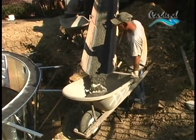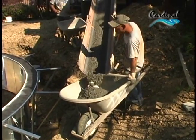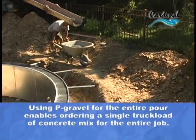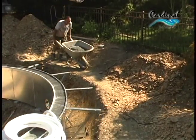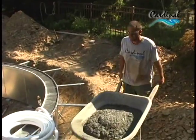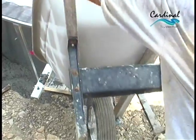The collar should be 6 to 12 inches of concrete mix. Either footer mix or 2,500-pound mix can be used. When installing stone coping in addition to a collar, use pea gravel for the entire pour. When pouring the collar, be sure any openings under the pool walls are filled.